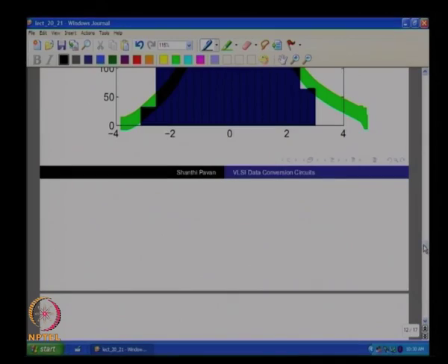So, now we will take a look at why you cannot go on putting integrators in the loop, going on increasing the order of the noise transfer function, in other words (1 minus z inverse) to the n, where n is a large number, with the motivation being that you want to reduce the in-band noise. This is not quite a viable thing in practice, and we will now go ahead and discuss this.